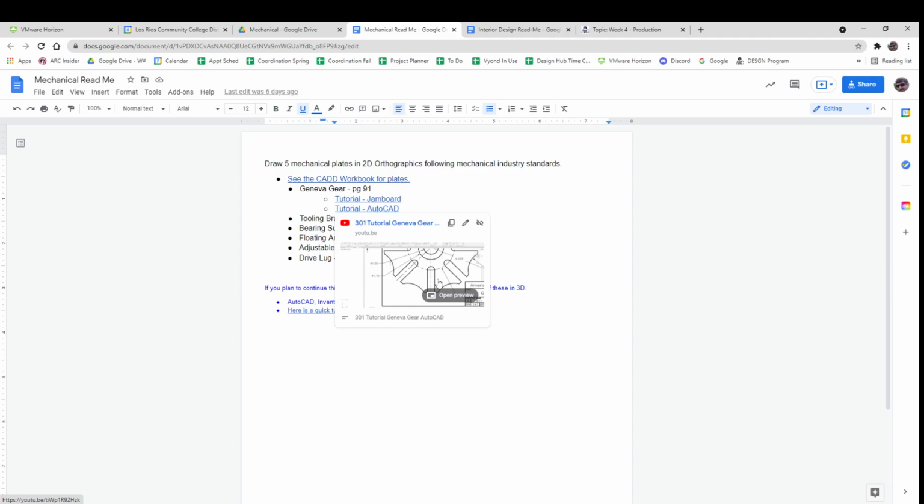We actually made what was called a clamshell cutter. You'd open this thing up like a clam, stick it around the pipe and lock it together, and then the head would go round and round, and the tool bit would feed in as you go. And every time it went around, a Geneva gear hit a little pin and forced our tool bit in, whatever we set on the lead screw. I mean, it was Geneva gear, lead screw, tool tip force.